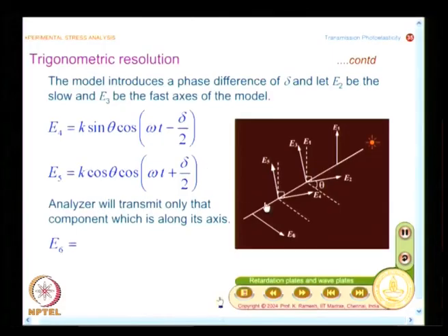Theoretically, when you are looking at a plane model, it is as thin as a plane, but physically we use a finite thickness. So, we bring in some engineering approximation and we also say that the principal stress direction remains constant within that thickness. And we do this as two operations. First, there is the intensity amplitude: the amplitude of the light vector changes. The second case, we put in the retardation appropriately, then it comes out.